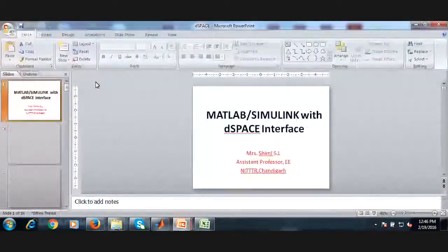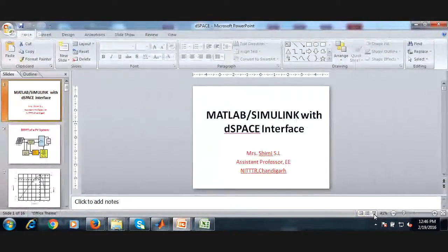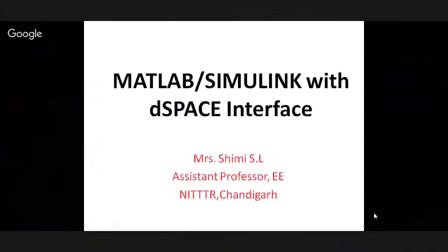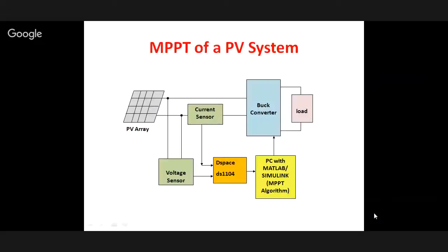So with dSPACE, even Arduino, all these things you can just directly implement. The same concept only, MATLAB Simulink with dSPACE interface. So here, for a simple example, I have taken a PV system, okay, and I want to track the maximum power point.